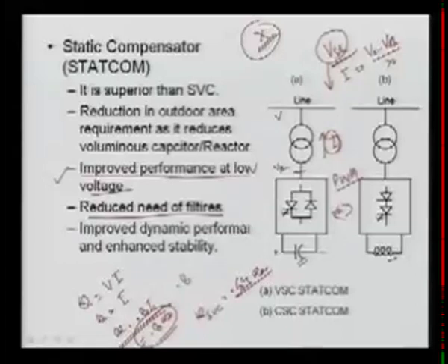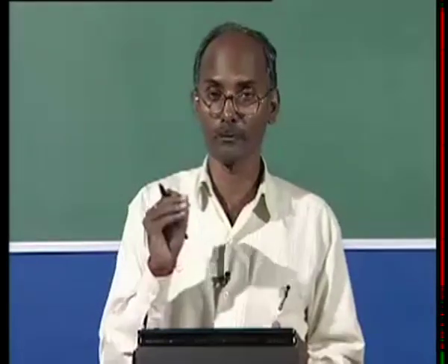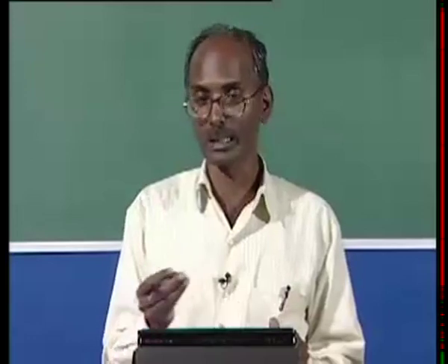And the dynamic performance is better, and the enhancement of stability will also be better. We can understand this part only if we go through the characteristics of these devices. Before that we have to go through the basic fundamentals of stability, how it is going to improve, and then we will see that STATCOM is better than SVC. But the SVC is the oldest device in the FACTS family, and that's why it is still cheap.